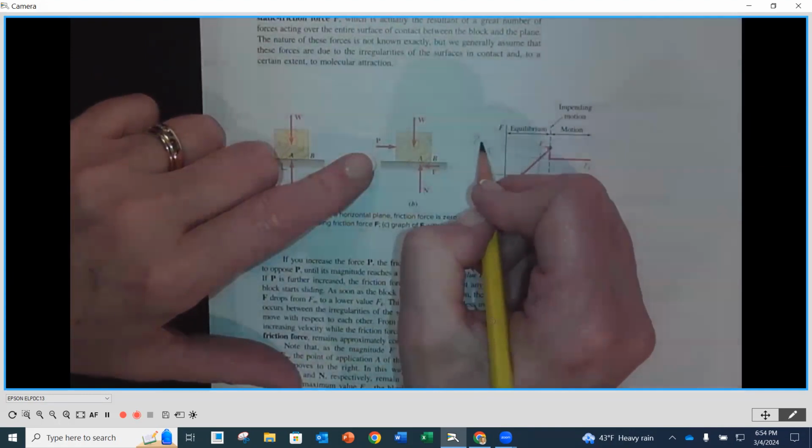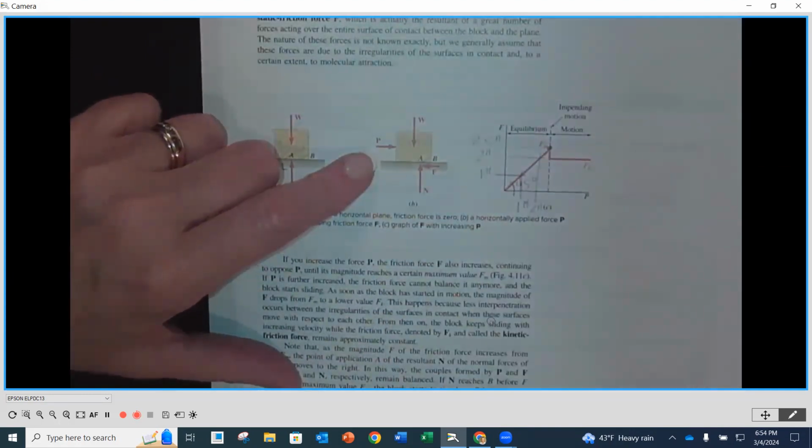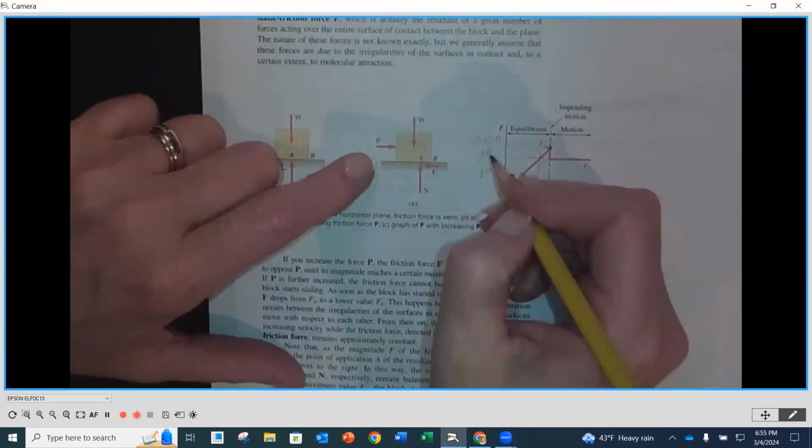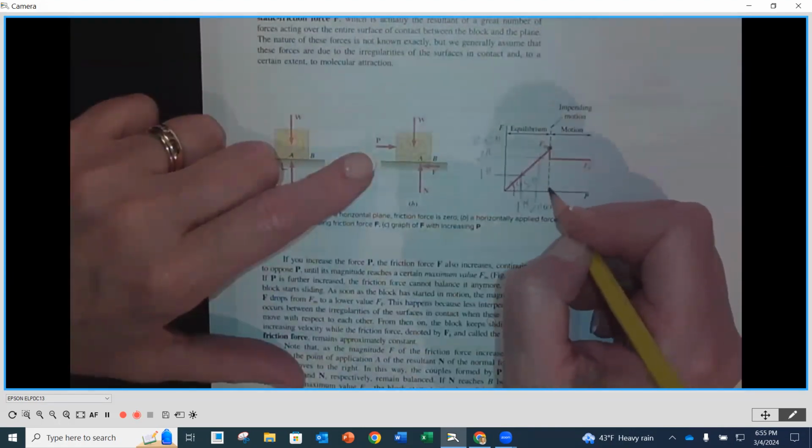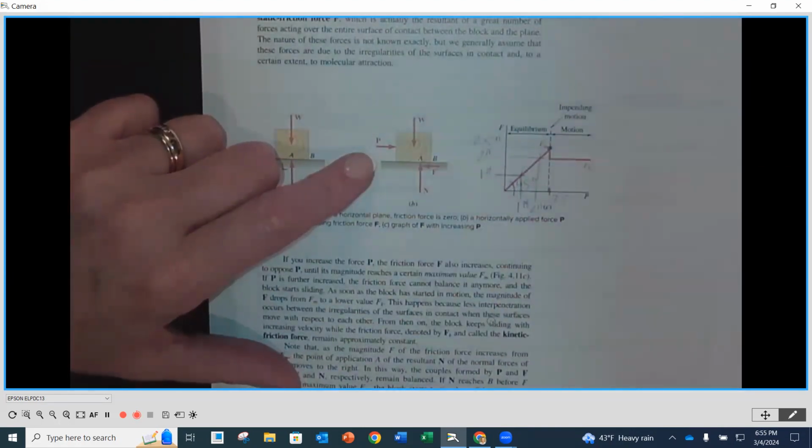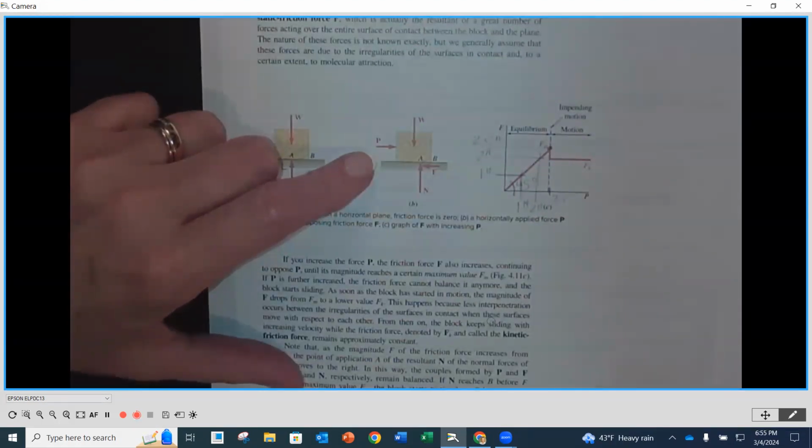And based on what I've got here, I'm going to say 2.5 pounds. Now, I'm not quite moving. I'm almost moving, but it's almost going to kind of go over that hump and it's going to start going. So the maximum friction force and that pushing force, I'm still not moving, is going to be 2.5. But when I get just over that, I'm going to start moving.